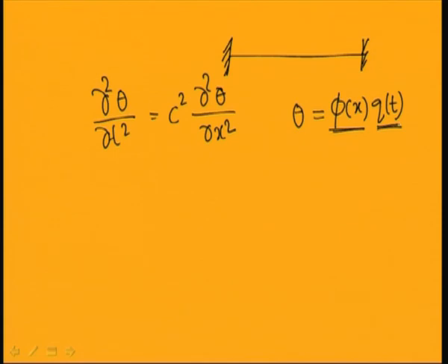You have already derived this equation by using the Hamilton principle, and you can also derive it using Newton's method. In the Hamilton principle, you take the kinetic energy of the system and the potential energy of the system. The potential energy is the strain energy stored due to the shearing effect of the shaft. By taking these you can find the Lagrangian of the system, L equal to T minus U, and then apply the Hamilton principle to find the equation of motion.